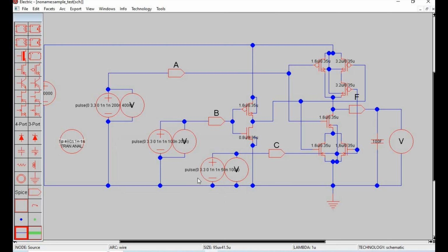So again, assign C as your least significant bit, starting with 50 nano and 100 nano as your period. Then double it up to your most significant bit. If you need an inverter across your input, just add an inverter depending on your derived equation.